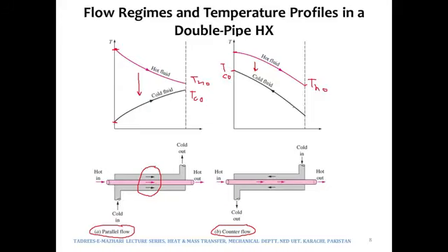The reason is that on its way out, the cold fluid is not exchanging heat with T_H,out, rather it is exchanging heat with T_H,in, since it is a counterflow heat exchanger. Therefore its temperature may exceed T_H,out, but it will never exceed T_H,in.